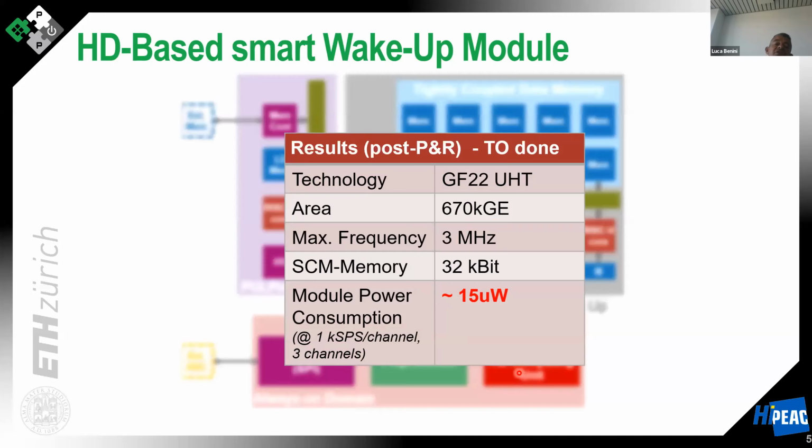Just to give you a feeling, this wake-up processor consumes only a handful of microwatts, so it can be always on without exhausting the battery of your system, while if you turn on even only the basic single processor in the system that you see in the SoC, we have to be ready to spend tens or hundreds of milliwatts.